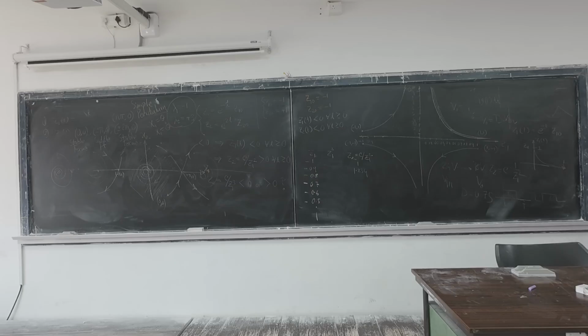If you need more output, then you have to increase the T on, right? If the duty ratio is 0.5 and you want only 12 volt, then it would be 50%, 50%. That means half T on, half T off. But if it is 0.75, that means you have to keep the switch on for a longer time. So that is a perfect example.